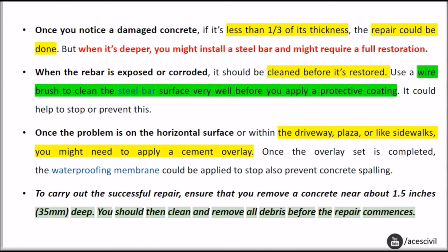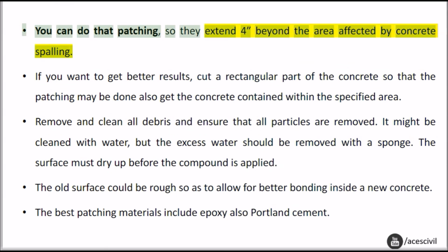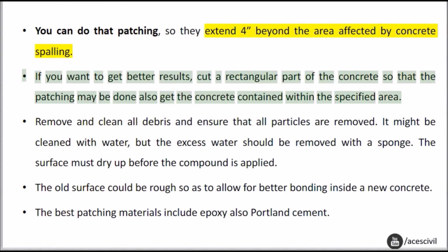You should then clean and remove all debris before the repair commences. You can do the patching so that it extends far beyond the area affected by concrete spalling. If you want better results, cut a rectangular part of the concrete so that the patching may be done. Also remove the concrete contained within the specified area.